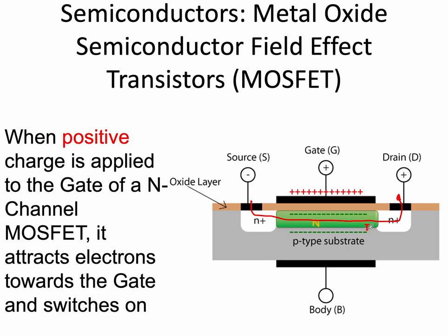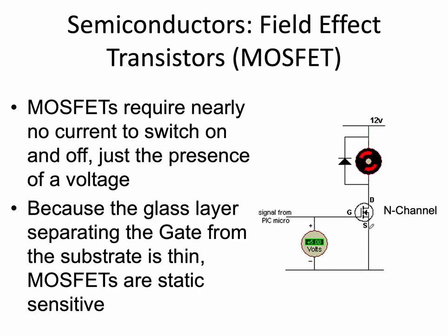And this is where things get interesting. With a very, very tiny applied voltage here, you can turn this thing on and off. And this is where it gets fun. And so this is the schematic for an N-type MOSFET. Even a small positive voltage, turning it on or off, can run large motors and devices that are connected to much larger voltages here. So the positive voltage here, positive 5 in this case, to the gate turns this on and can run a large motor running on 12 volts DC.